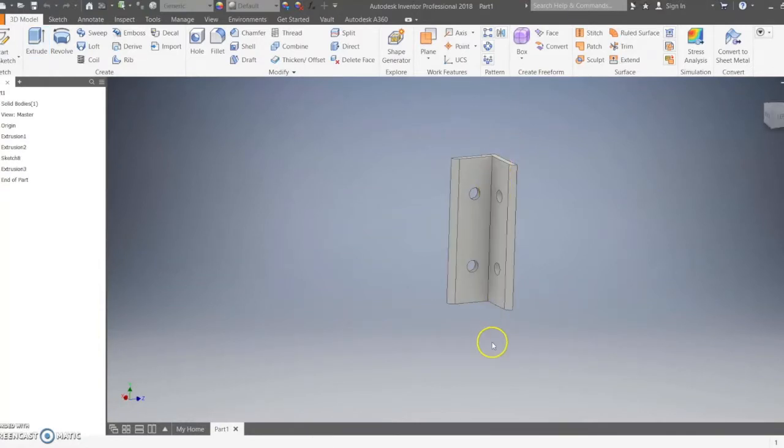After finishing the holes on one side of the part, you can repeat the process for the second side of the part to get the same result. Now, we're going to create the two parts for which we're going to use this to attach. To create a new part, there's a New button in the top left corner. If we click the arrow next to that, it will bring a drop-down menu in which you have 4 options. Press the Part button to open a new part.